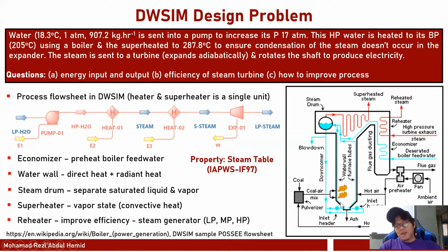It's just that the first part is subjected to direct heat. Basically, you really have a flame, and it's like when we cook our water, right? So whatever heat is used to boil the water, that's direct heat. And then the hot air will travel upwards, and it is still quite hot, by the way. It's not cold. So it's going to heat up this saturated vapor to form superheated steam.